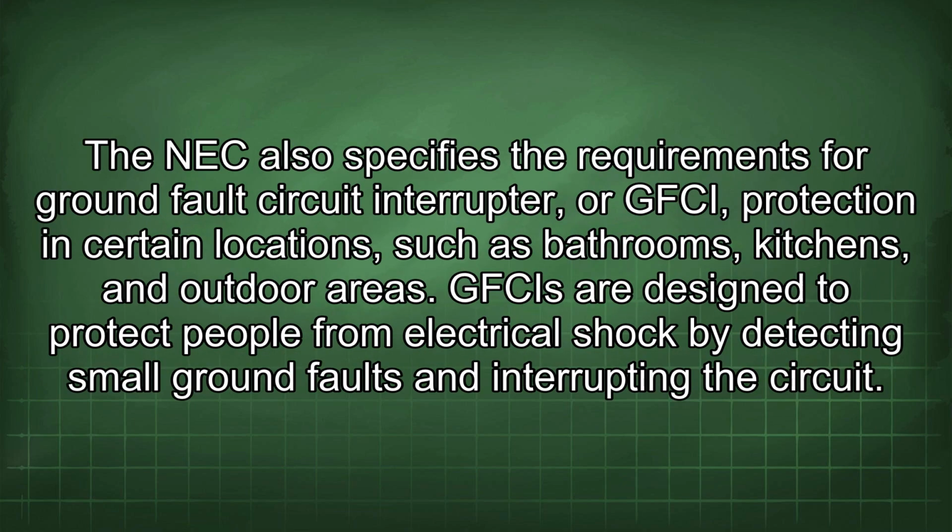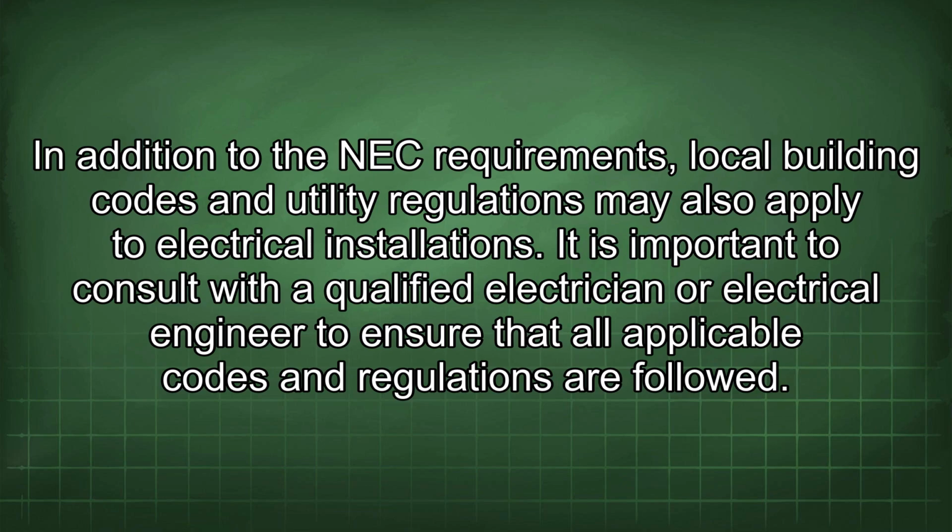The NEC also specifies the requirements for ground fault circuit interrupter, or GFCI, protection in certain locations such as bathrooms, kitchens, and outdoor areas. GFCIs are designed to protect people from electrical shock by detecting small ground faults and interrupting the circuit. In addition to the NEC requirements, local building codes and utility regulations may also apply to electrical installations. It is important to consult with a qualified electrician or electrical engineer to ensure that all applicable codes and regulations are followed.